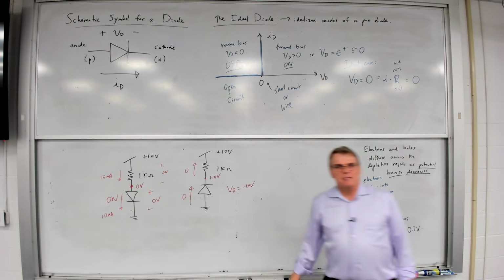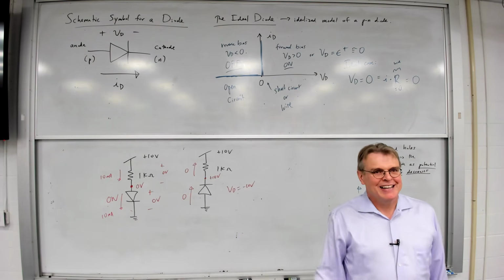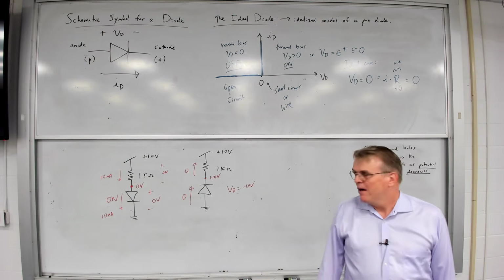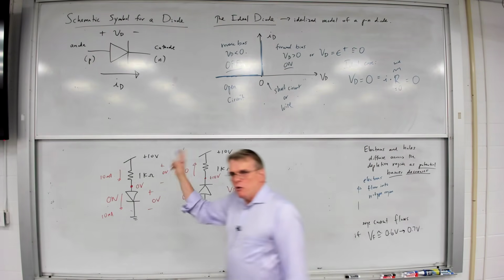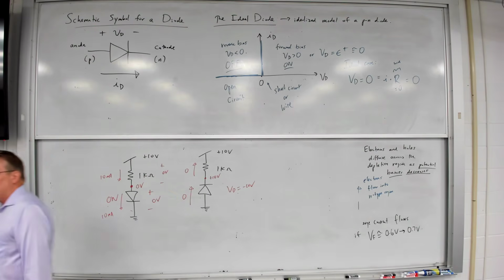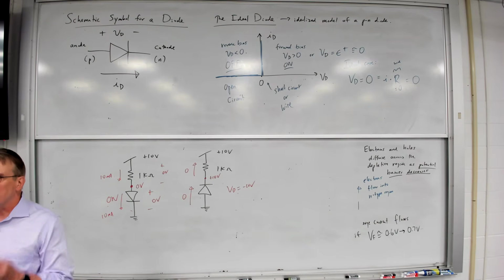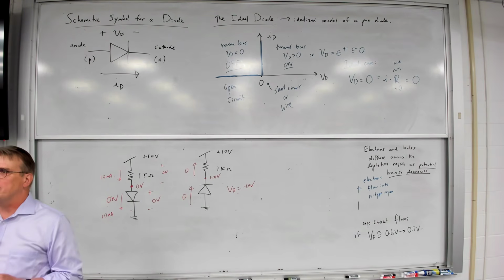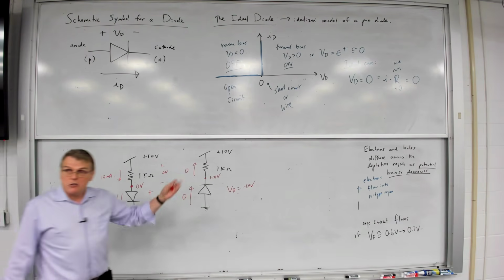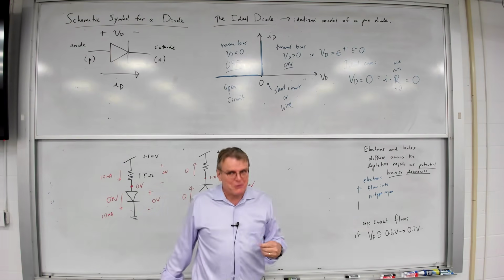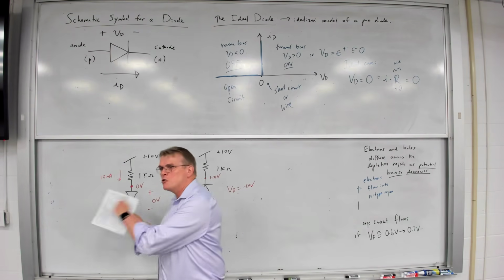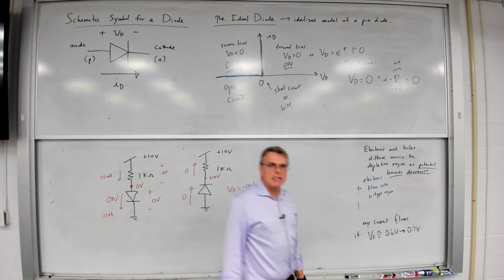Is that reverse biased? Absolutely. That diode is off. Okay, guys, you're going to be doing this for the rest of the semester. You'll see a circuit. Rarely can you just look at a circuit and tell what the operating condition of the device is. You make an intelligent guess or assumption, if you want to call it that, but then you check and see if it makes sense.